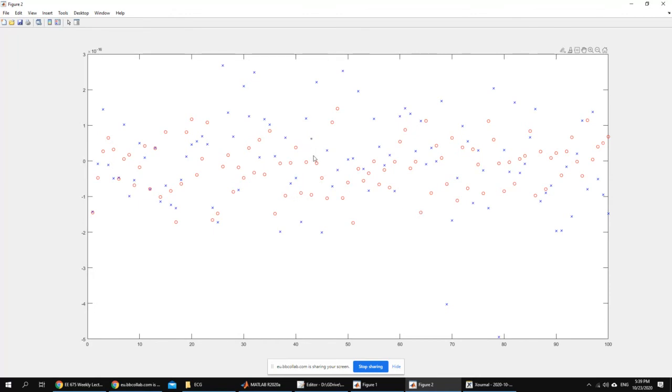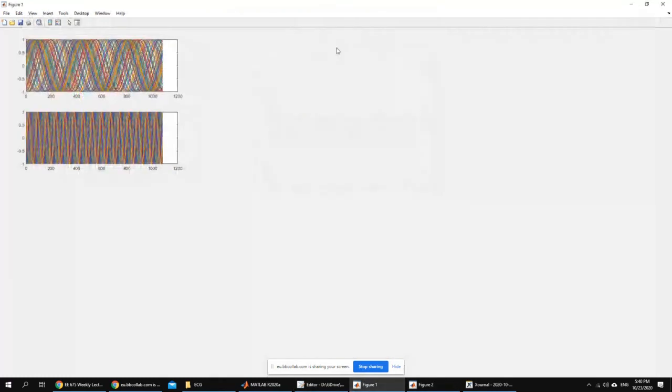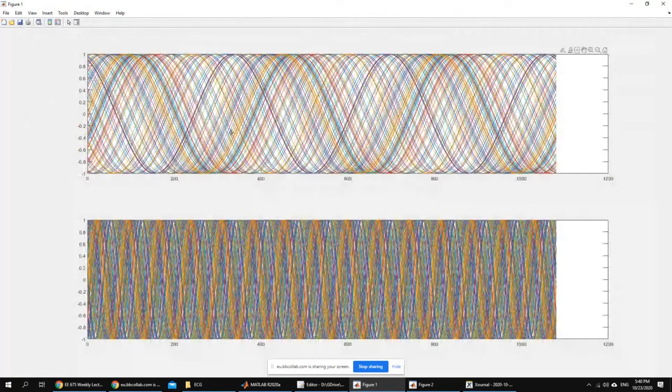Actually, there is no separation. If you look at these, it's all over the place. Basically, you have the values anywhere. The chances of being a circle or an X is probably the same. So it doesn't seem like this will be a useful feature to use, which makes sense because the signals we use actually both have a mean of 0. The theoretical signals we use are both sinusoidal signals. When we have many signals, each one of them is expected to have a mean of 0. What we're getting here makes sense. The mean is not discriminating here.